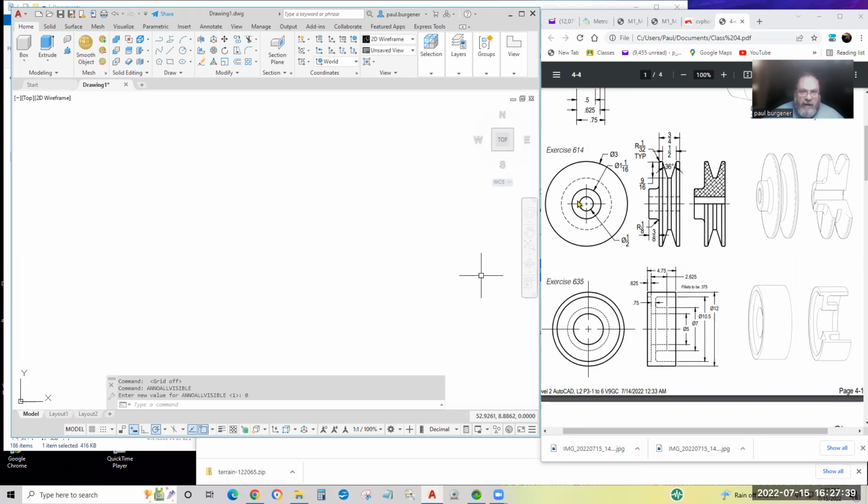Getting most of the horizontal lines is easy because the diameters are here, but you don't know the diameter of this hidden line there. It's got to be subtracted from the top. Looks like that 9/16 is a little off. I'll pretend I didn't see that. Let's create the circles, and the outer one I can simply offset 9/16 of an inch to get the bottom of the V. We'll go to the circle command.